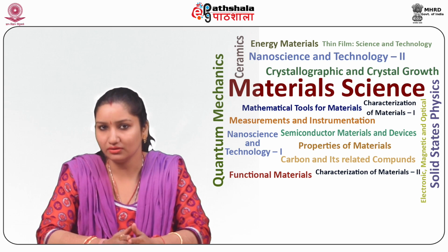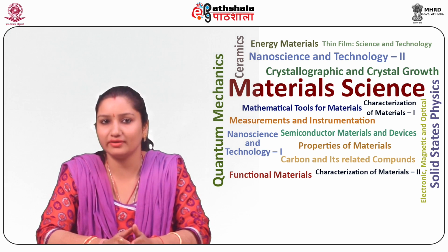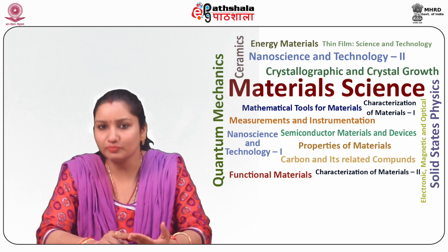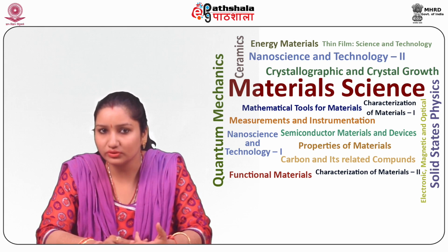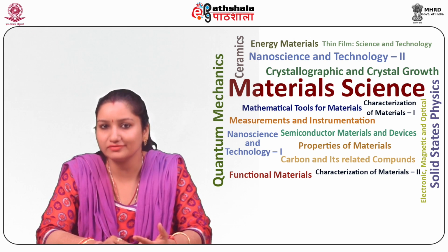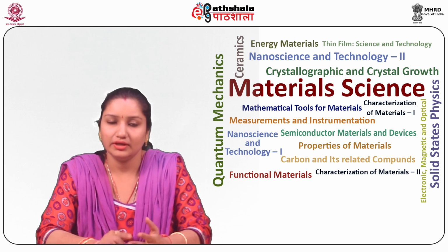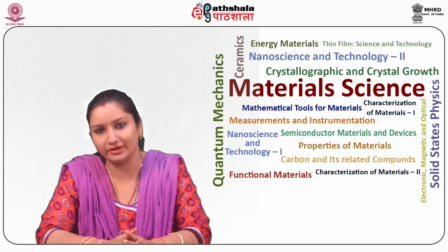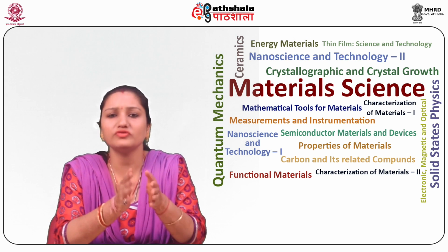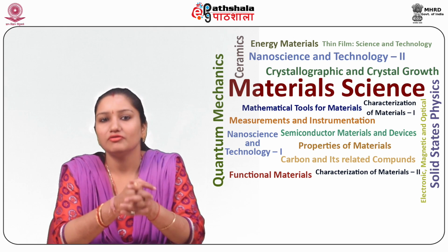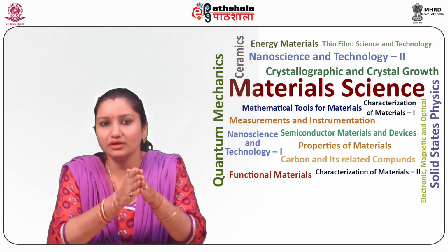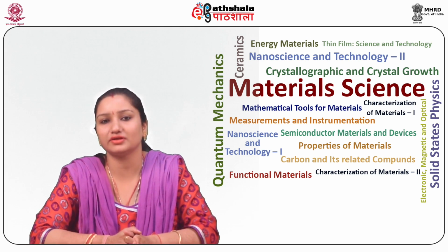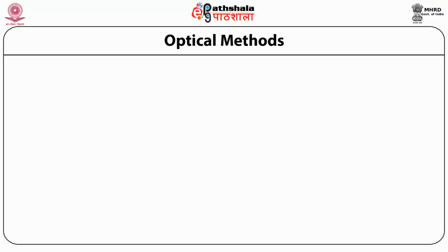The important criteria include properties such as film thickness, film transparency, film hardness, thickness uniformity, substrate smoothness, substrate optical properties, and substrate size. In many cases, there is no single best technique. The most useful techniques for determining film thickness include multiple beam interference, ellipsometry, quartz crystal, and stylus technique. So let us now discuss the optical methods for determining the film thickness.